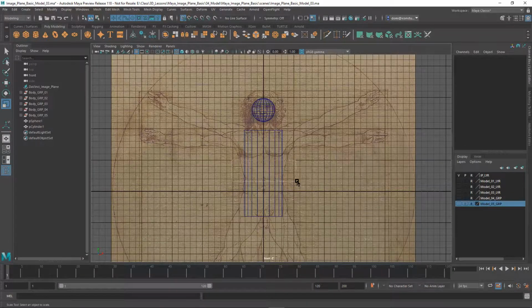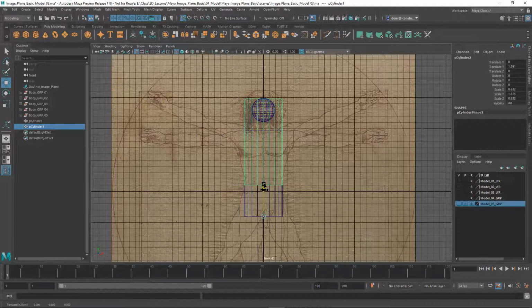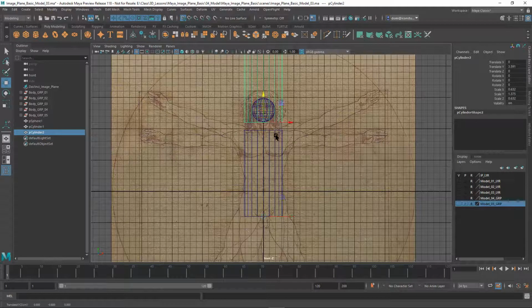So now I'm going to select this, and I'm going to do the move key. And then in a previous lesson, we showed you how to move and clone. So if you hold on your shift key and you're moving your object, you can move it up. So now it's snapping to grid right now. I don't want that. So what I'm going to do, I'm going to do that trick again. I'm going to turn off grid snap and I'm going to turn off point snap. And I'm going to pull this down and boom, voila.